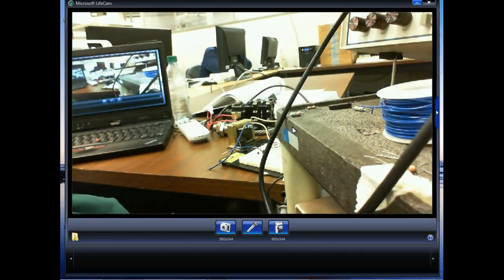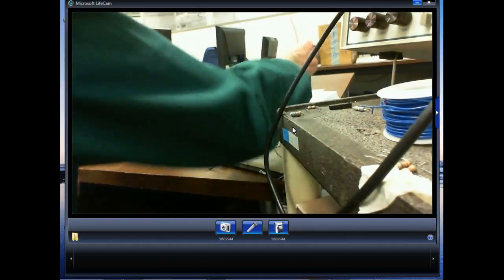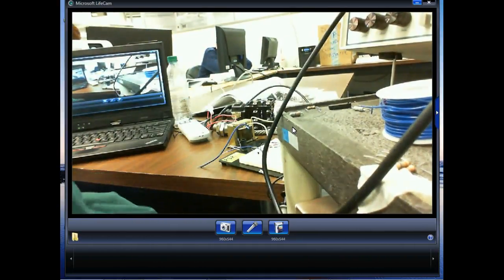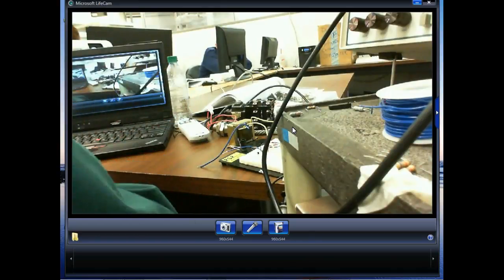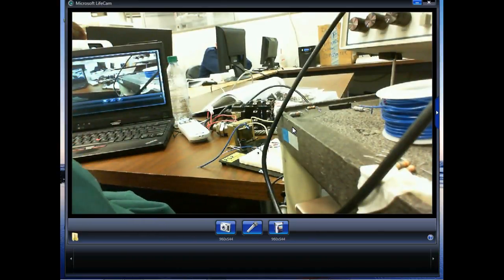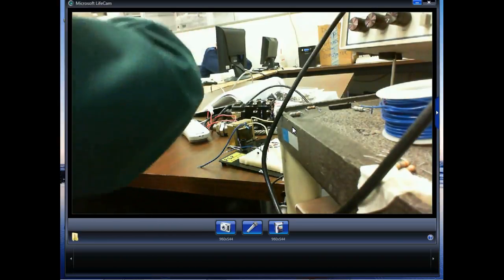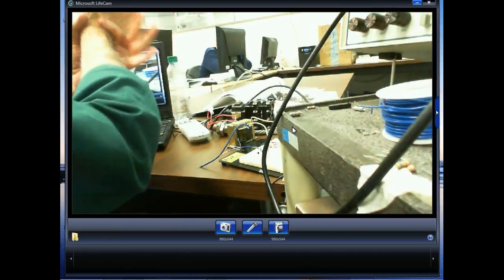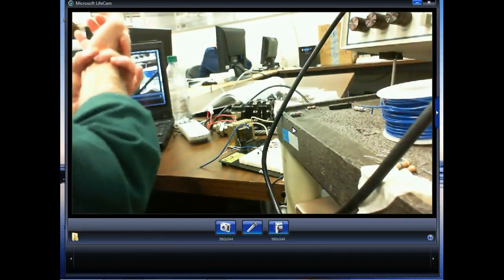It's not that hard. I'll show y'all some of the equipment. The static mats and the static armbands are less than $5, and if you're going to work with these things, you probably need to get you some. I think on the ABB robot, when you open up the controller, they've got a static armband in there already.